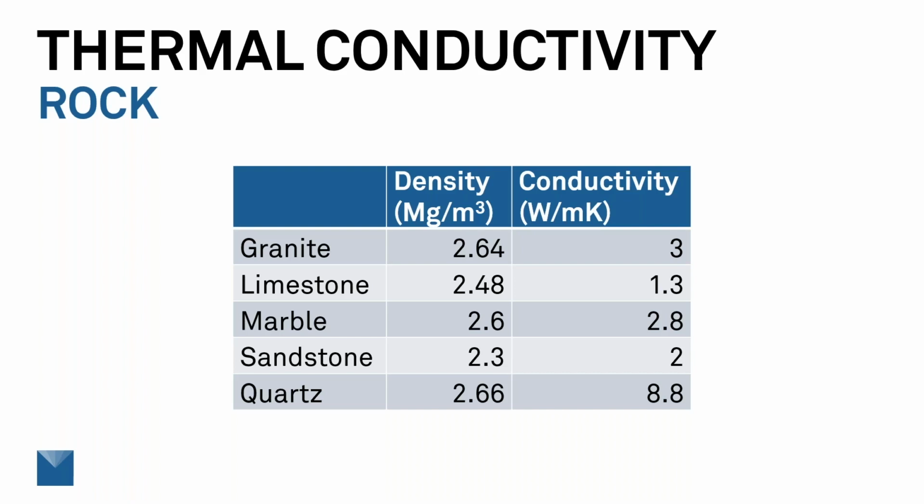Now, the thermal conductivity of rocks can vary pretty widely, and if the rocks are porous, the water content can vary, and that will change the thermal conductivity of the rock. These are complications that you need to be aware of, you need to look out for, but for our purposes here, we'll assume that the conductivity of the rock can be measured and is constant with water content.